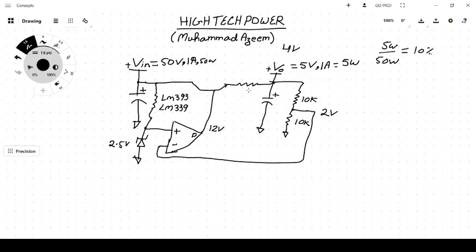So they then suggested a clever way to overcome this problem. What they did simply is that, instead of inserting the resistor in between the emitter of the transistor and the output capacitor, they inserted an inductor. So let's see how it behaves when we insert an inductor.